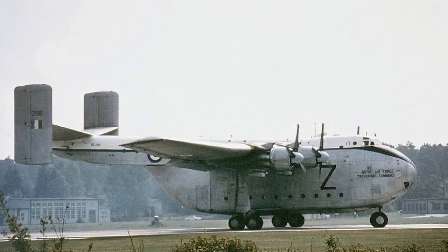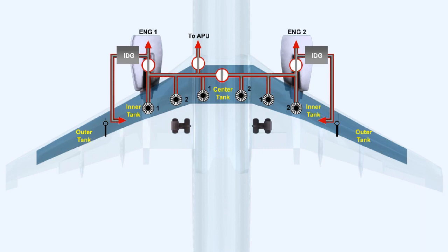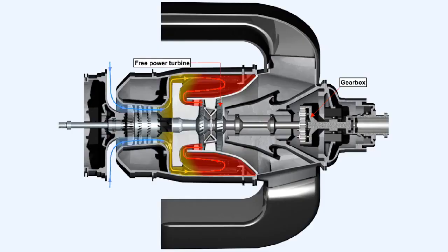While earlier aircraft used the piston engine to drive their auxiliary power units, it soon became obvious that the gas turbine engine was safer, lighter, quieter, and more reliable. The gas turbine engine auxiliary power unit uses AVTUR, which is the same fuel as the main engines use, so the problem of fuel storage and fuel management systems is minimized. The type of gas turbine engine normally used to drive auxiliary power units is a turboshaft engine with a free turbine.